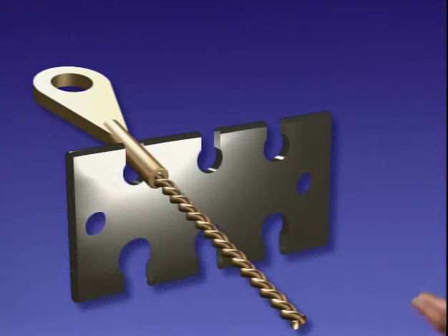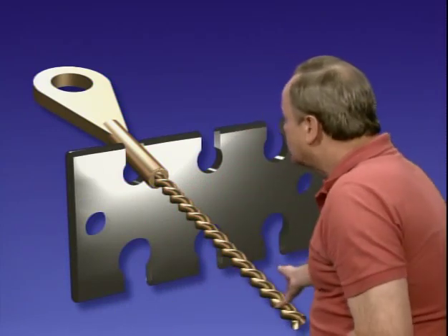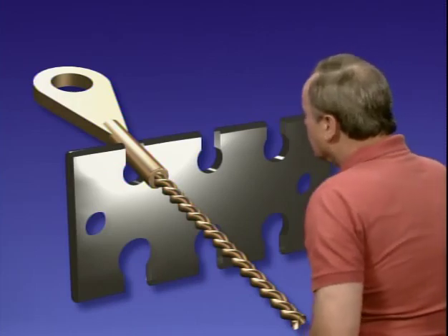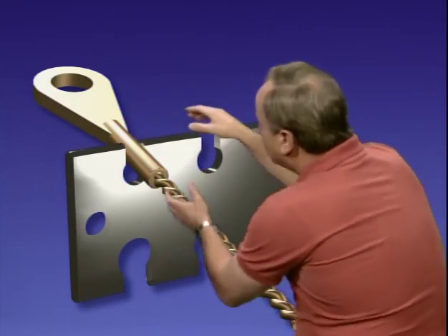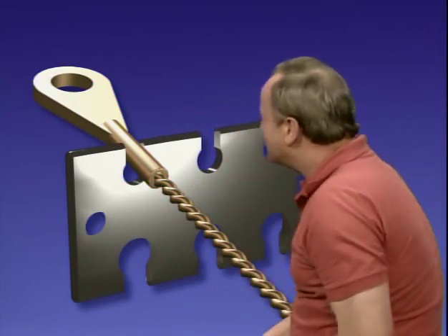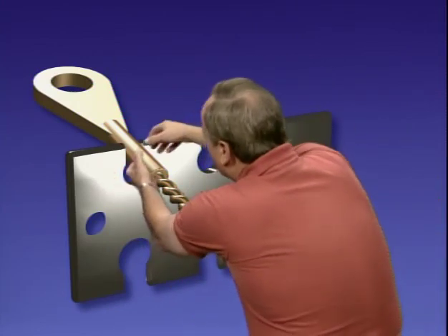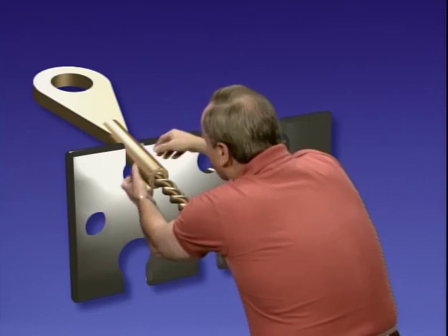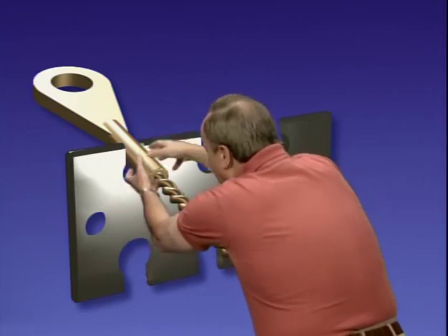Now, let's assume that you've just inspected an aircraft, and one of the things that you have decided is that you need to replace the control cables. Well, when you do that, one of the things you'll also need to do is reattach a terminal to a cable. Now, how are you going to do that? Well, these days, the way you do it is press it on, or what they call swaging it on. This is called a swaged terminal.